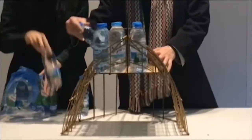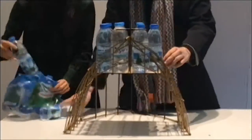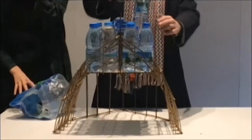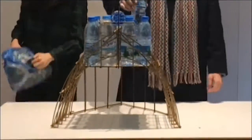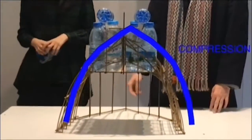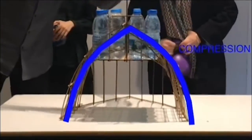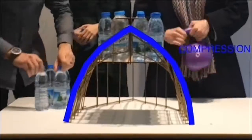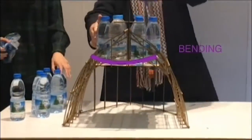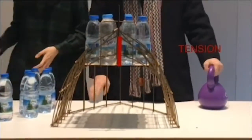In the final model we took forward these ideas of using systems that are similar to churches and designed a structure that would, with the use of various arches, spread the load throughout to different points where the structure would touch the ground, where each arch system was then pinned together at the bottom. This pin and tie system remained in tension under the weight or force from above. By pinning it at the base, it meant that the legs would not move outwards and they would stay stable while the load was applied.